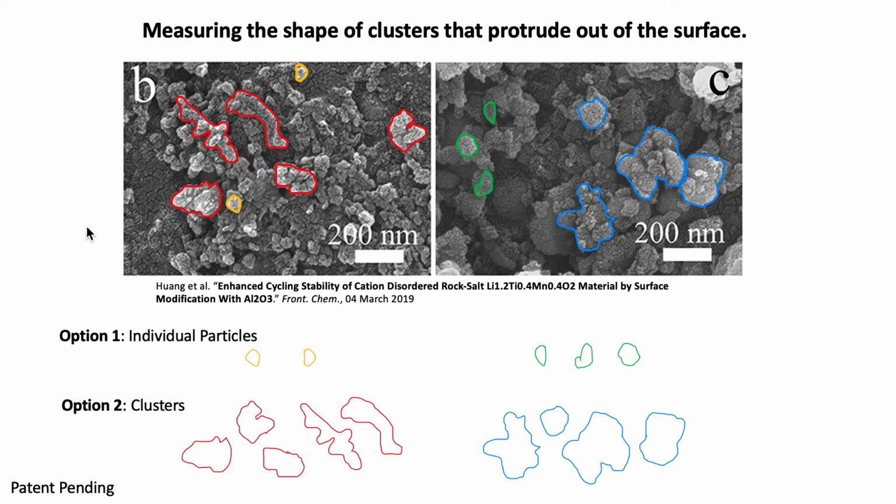And here, just to highlight another type of complexity that the LCPC can handle, the particles that protrude at the top of the deposition layer. Here on the left, long elongated clusters are formed, while here on the right, they form these clover clusters. And so while both conditions do share some amorphous shapes that are similar in size and shape, they also have very distinct morphologies that are specific to each condition. And the LCPC can measure the distinctness of each morphology, and of course, tell you about the distribution and ratios between these different morphologies in each condition.